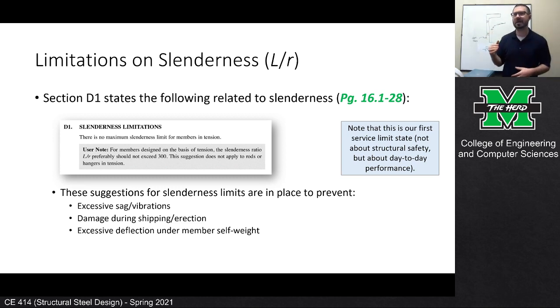I remember being at a fabrication shop and there were some I-beams, and these I-beams were 100 feet long and yay deep. And because I was bending about the weak axis, I was able to just bend it with my hand. Not because I'm some Kryptonian Superman or something, but because in that direction they were pretty weak. And that's not how they were intended to be in their final state, but that's kind of the point I'm making. Slenderness limits are really important, and this term L over r, which is our definition of slenderness, is going to be really important later.